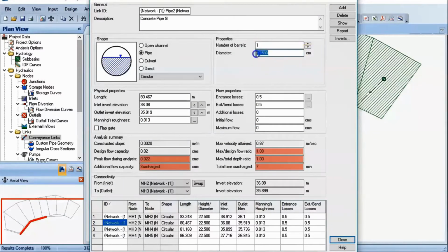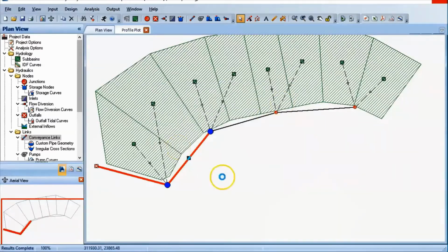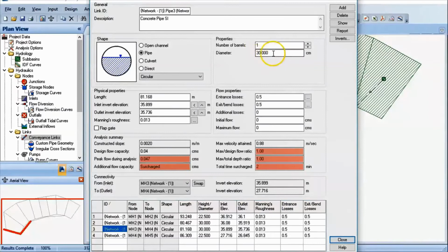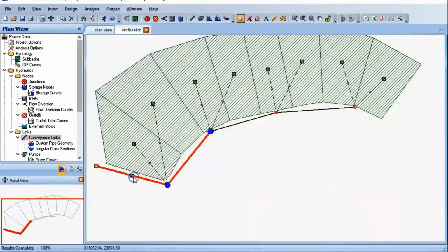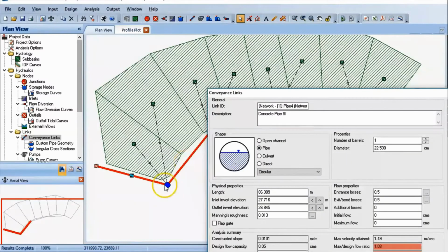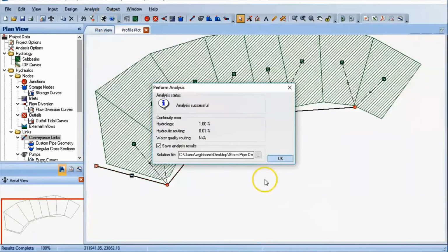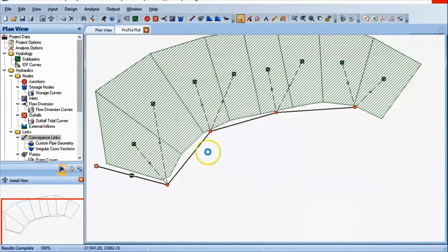and then you can actually go redefine your pipe sizes. Now the pipe sizes, you literally need to select per pipe to change the pipe sizes, diameters, and then you can rerun the analysis. So as soon as you do that, you can see the modification has been changed, and I need to go and make sure the last two is also designed. So you do that manually, one pipe at a time, which is a bit tedious on my end, because you can think if you've got a big stormwater network, how long this is going to take.